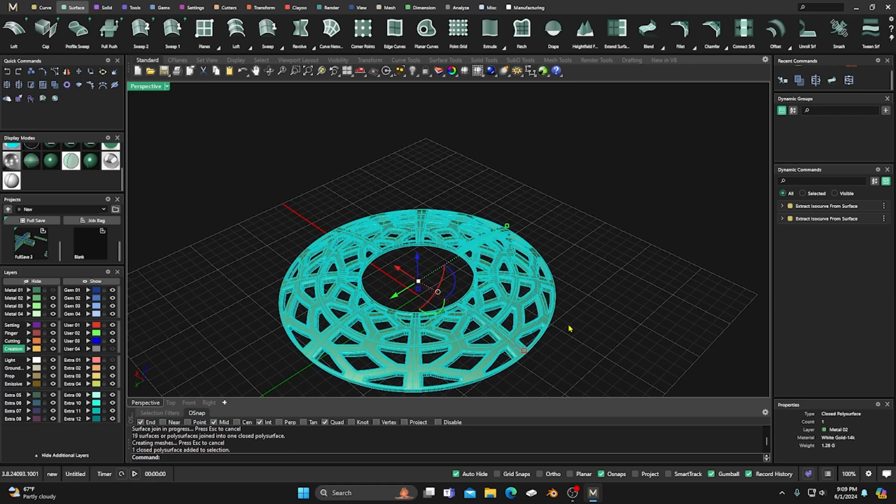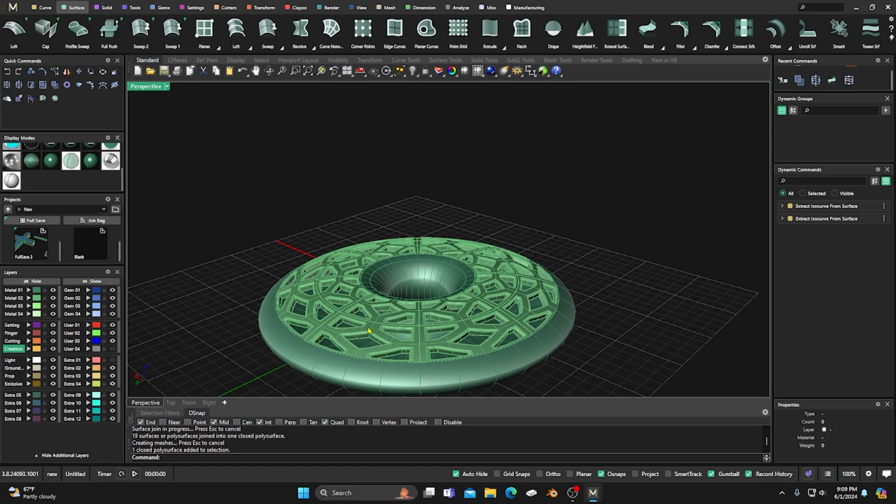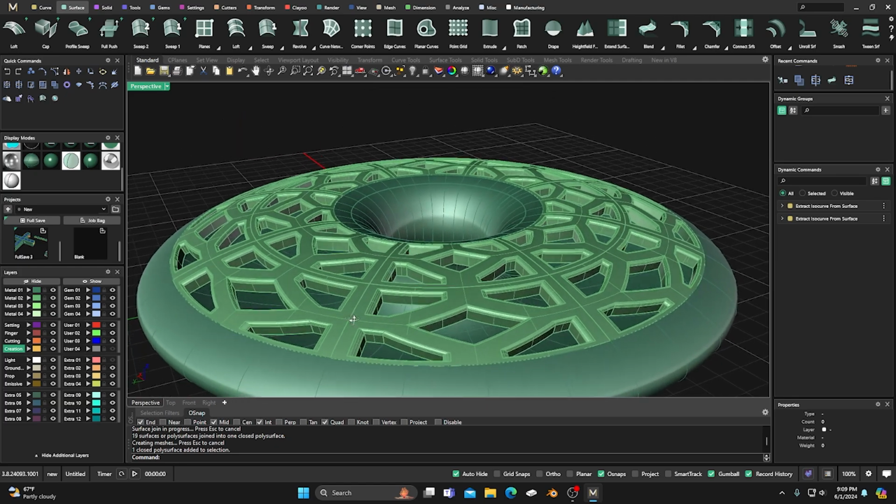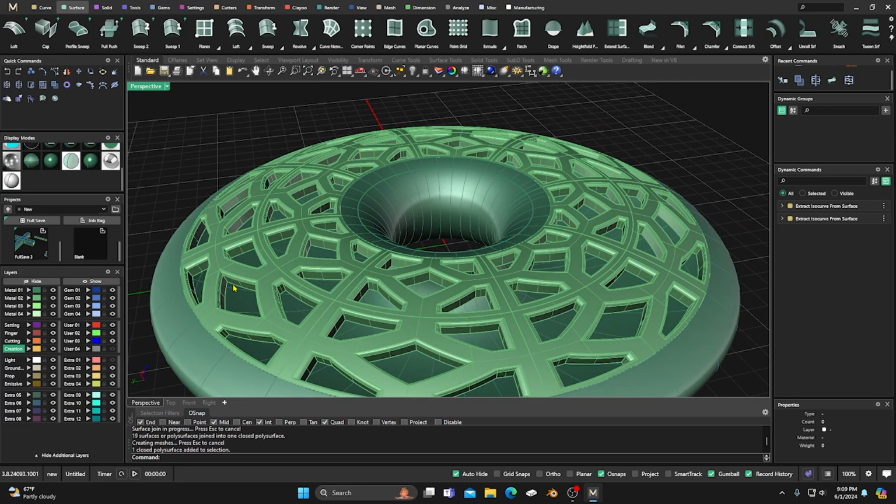And if we select it, it says close poly surface now. So if we bring back our item here, oh, I did not duplicate that surface. That is a major bummer. Before I did all the splitting, I should have duped in place that surface and put it on a different layer because I only have the top layer.